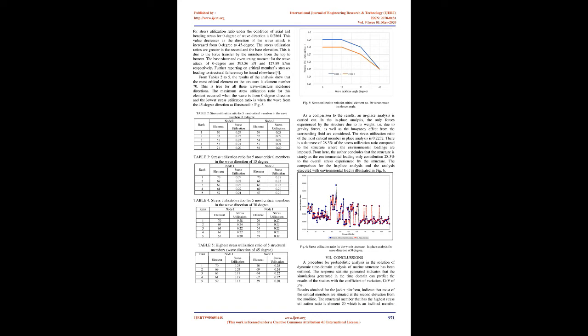6. In the present case study, Tp equals 9.9 s and γ equals 3.3. Thus Tz equals 7.73 s. Hence V_ηmax equals 0.078, and V_Fmax equals 0.156. These values agree well with the observed values, V_ηmax equals 0.07 and V_Fmax equals 0.145. From here, simulation lengths can be established.